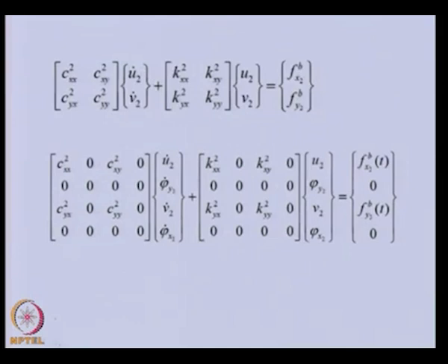On the same line for bearing 2 we can write, only the bearing property, the superscript is representing bearing 2, it is not the square, and if we expand this we will get similar to the previous one, only here subscript 2 is coming and the field variables are corresponding to node 2, because these are attached to node 2. These are the fluid film forces.